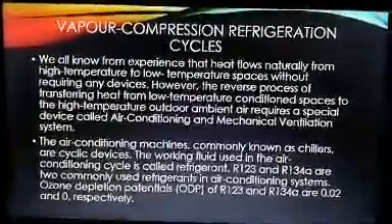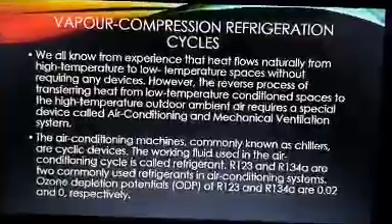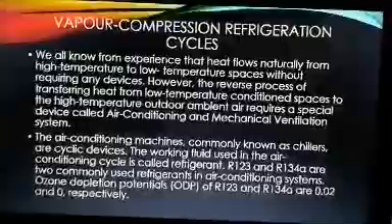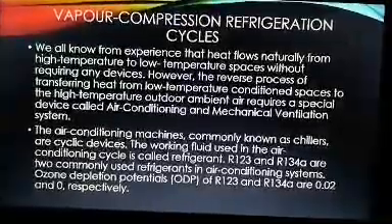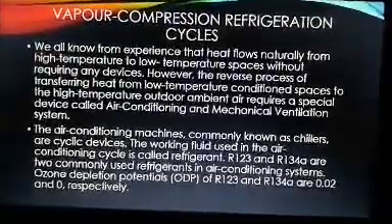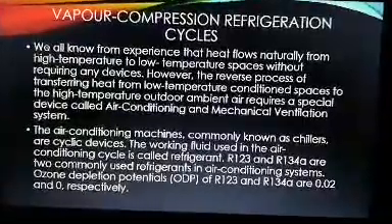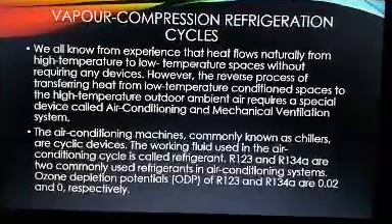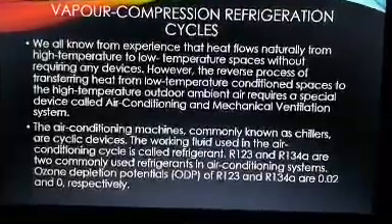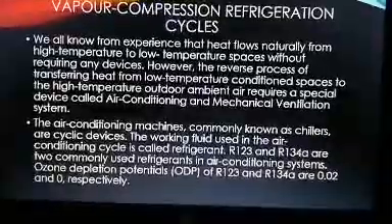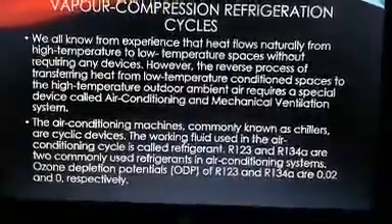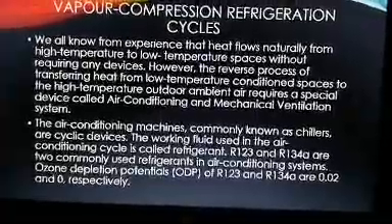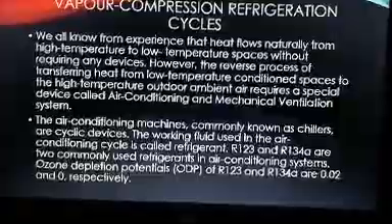Vapor compression refrigerant cycle. We all know from experience that heat flows naturally from high temperature to low temperature space without requiring any device. However, the reverse process of transferring heat from low temperature conditioned space to the high temperature outdoor ambient air requires a special device called air conditioning and mechanical ventilation system. The air conditioning machine, commonly known as chiller, is a cyclic device. The working fluid used in the air conditioning cycle is called refrigerant.